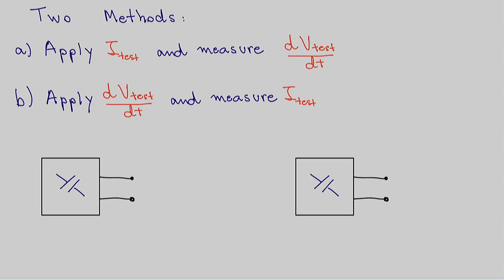In other circuits, depending on how the elements were connected, we would choose I-test because we knew the current going through the elements would be the same, making our equations simpler. We also had some conversations about whether it matters if I apply I-test or V-test. The answer was, it doesn't matter, but depending on how you choose, you might end up dealing with more equations than others. So in most cases, we try to simplify.